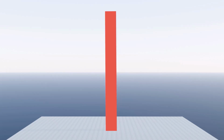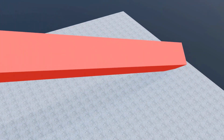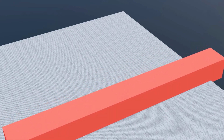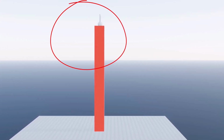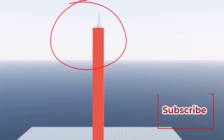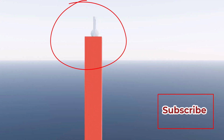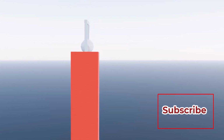Now, if I increase the wind strength in this Blender model, we can see that this building can easily collapse, because this building alone can't provide enough stiffness to prevent it from swaying so much and prevent this type of deflection. Now, when I make a TMD at the top of this building, the deflection due to wind is reduced significantly, and it is very helpful in the design of tall buildings.